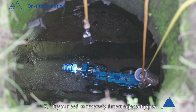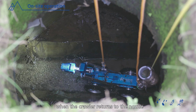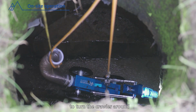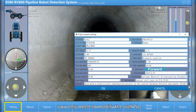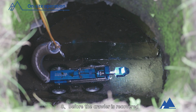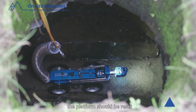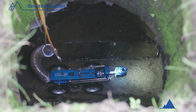7. If you need to reversely detect adjacent pipes when the crawler returns to the nozzle, lower the hook to cooperate with the cable to turn the crawler around. In the acquisition software, you only need to modify the well number to start the inspection of another section of pipeline. 8. Before the crawler is recovered, the platform should be reset. The lens should be tilted up to 90 degrees to prevent bumping.